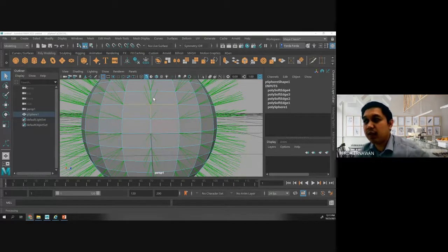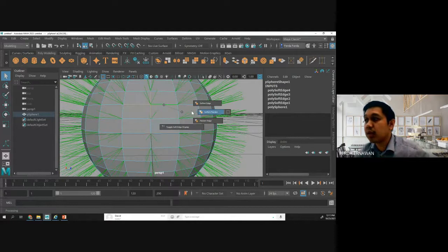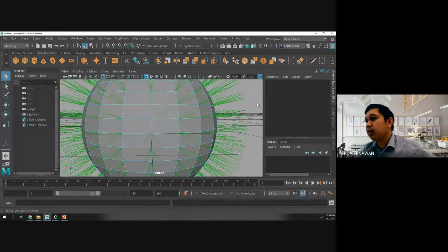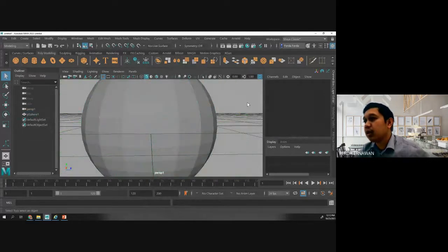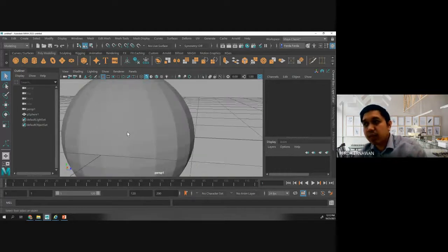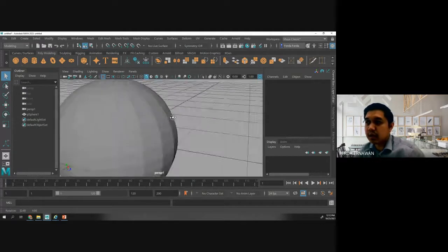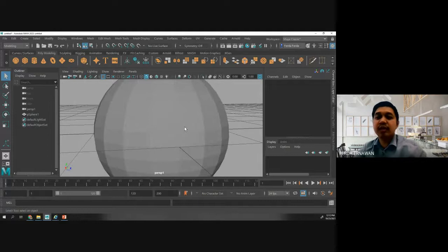Let's say I select four like this, and then press Shift. Press the Shift button, right click, then you choose soften edges. What you can see here, you have to return back to the object mode. Then you can see what's the difference. In the cube, you are not able to see here. This is the smoothened area, and this is the hardened edges. So you can change the smoothen and harden through this technique.